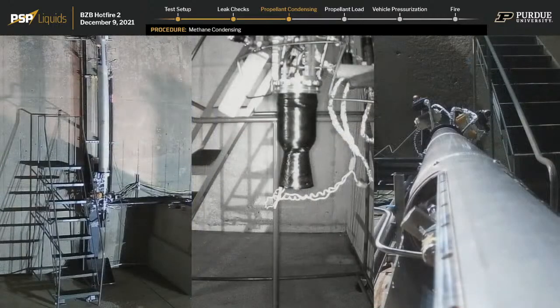So, when we are firing, let's talk about the heat deflector, or the flame diverter. What do we expect it to do? So the aim of the flame diverter is to make sure that the plume of the engine does not obliterate the concrete beneath it. And so this basically steel plate is subjected to, frankly, crazy thermal and gas impingement loads. So one thing we do to reduce that wear on the system is we flow water over the flame deflector. And so this will cool it down and make it so that we don't essentially obliterate our nice steel flame deflector. Right, and there is still some wear on the flame deflector after each operation.